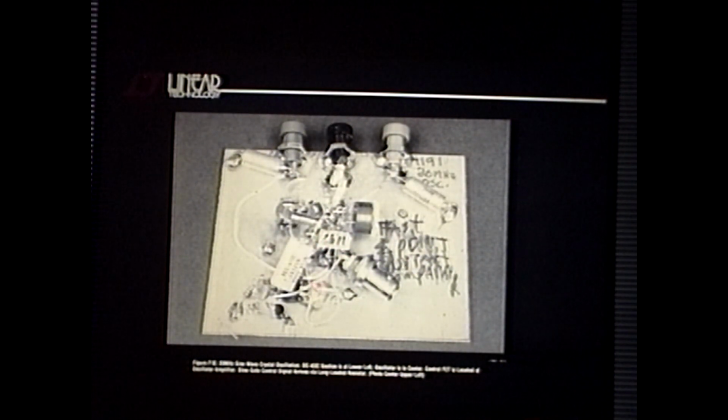Okay, the AGC stuff, this is pretty tightly wired in here, because I am worried about strays at 20 megahertz. But the AGC, that's pretty much low frequency and DC stuff. I can get away with garbage there. No sense wasting time.